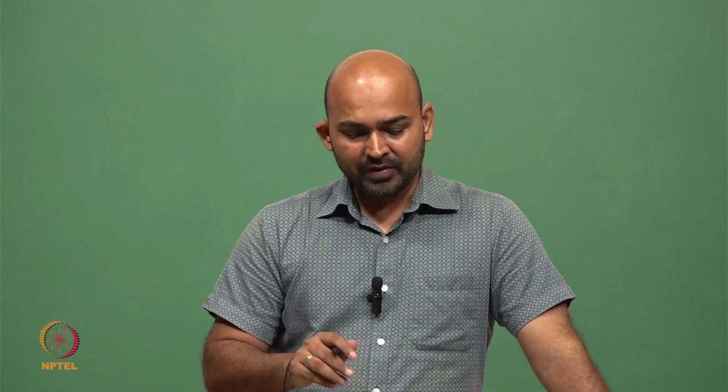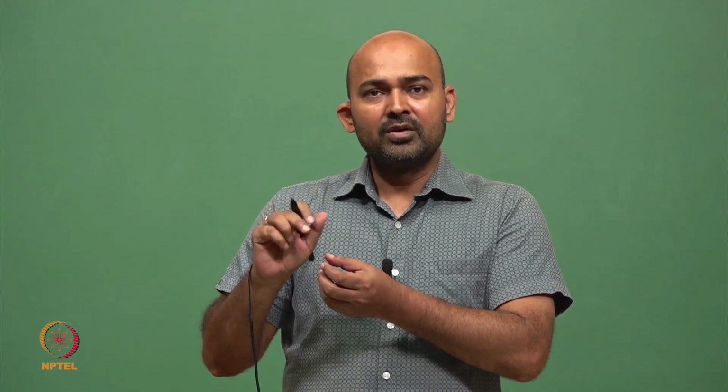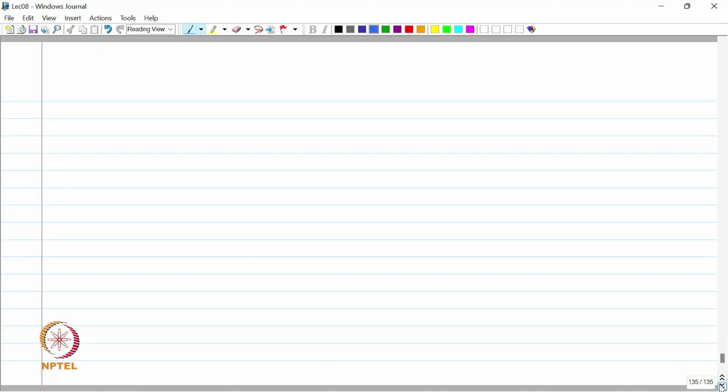So this is how a common emitter amplifier works. We will not go much into the detail of how it works. So this amplifier now takes the signal of millivolt range and converts it into a volt kind of range, which is now amplified to typically 1 or 2 volts or so. Now this amplified signal is applied to the Schmitt trigger.